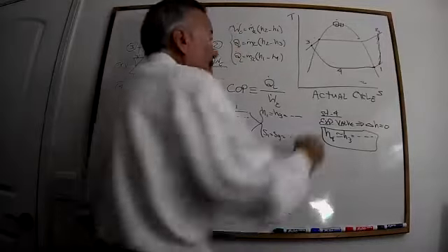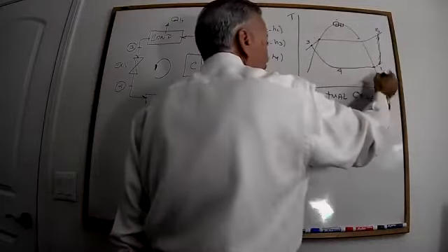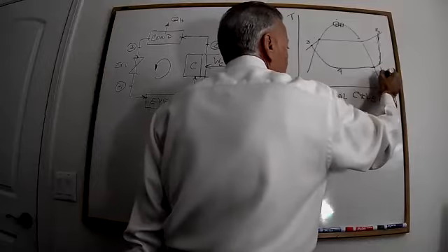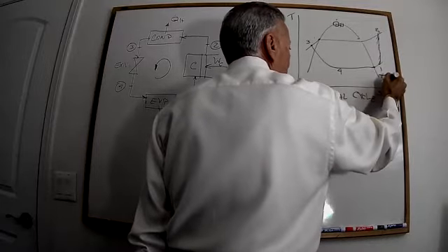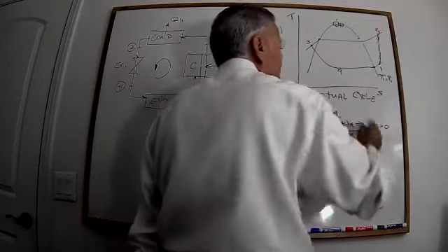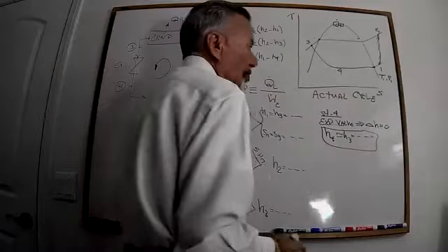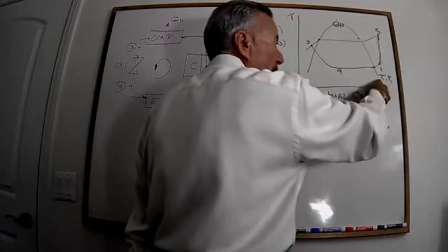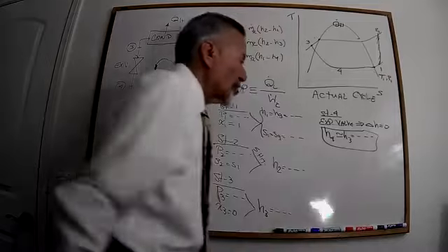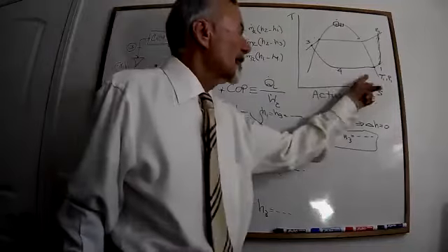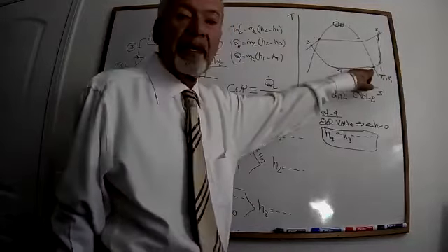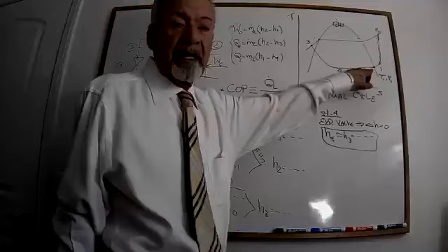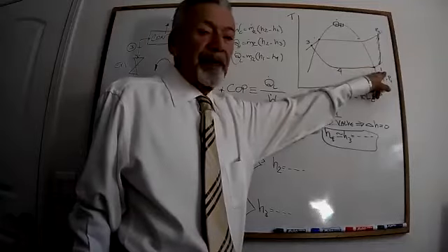In this case, you have to have the temperature and pressure. You always have the pressure at point 1, but you need another point of reference, and that's the temperature. Because you no longer can say X is equal to 1, because it's not. That point 1 is in a superheated state.